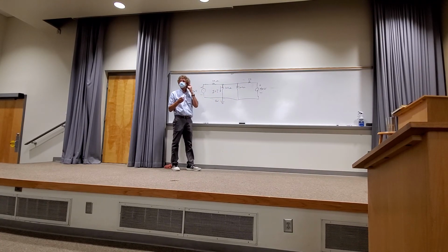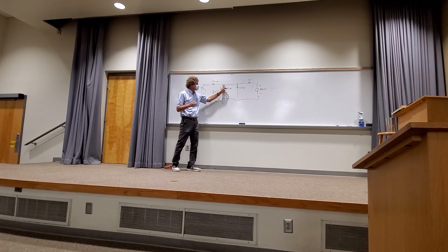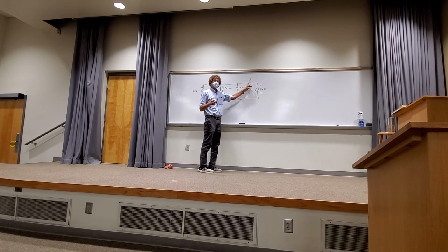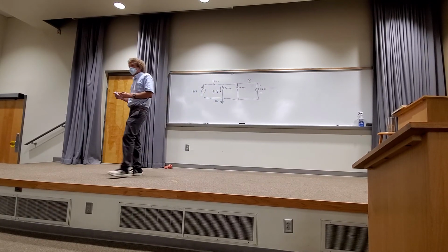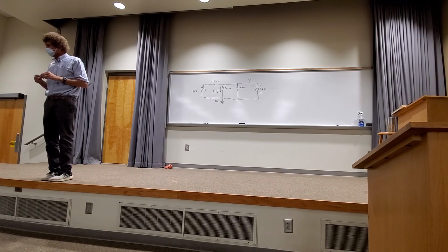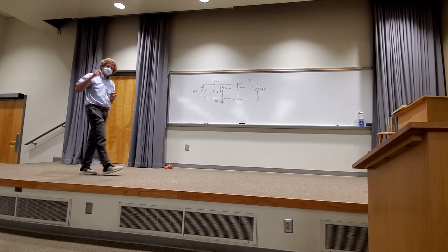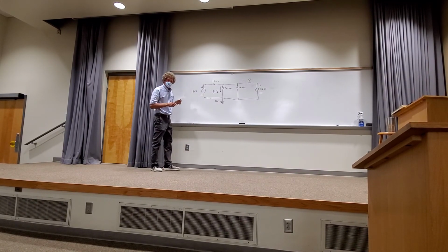If you want to know where the voltage is the same, take a marker, any kind of colored marker, and just start at one end of any component and move through all the connecting wires until you can't go any further. That has the same electrical potential, right? And anytime you have the same two colors across any two components, they're in parallel. That's the nice thing about it. When they teach you how to do circuit redraws, they say get some colored markers, because some people come up with bizarre ways of showing resistances in the circuits.